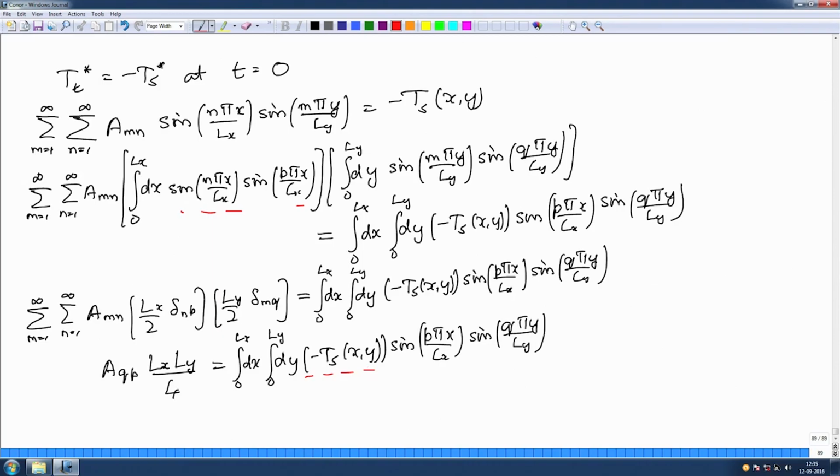So, basically we have to do separation of variables 2 times. The first to determine what is the steady temperature. In that case, we are just solving the Laplace equation for the temperature field. Once we have done that, we have got the steady temperature. We subtract out the steady temperature to get the transient temperature, and for that transient temperature we get the solution.